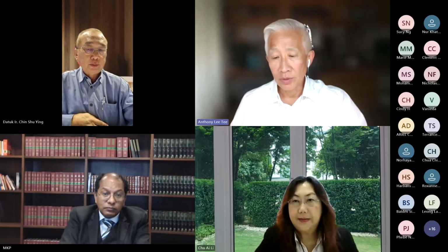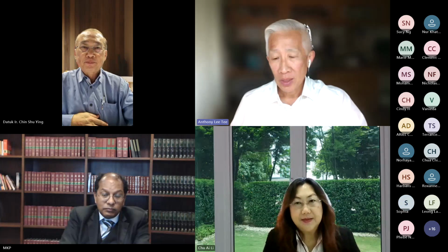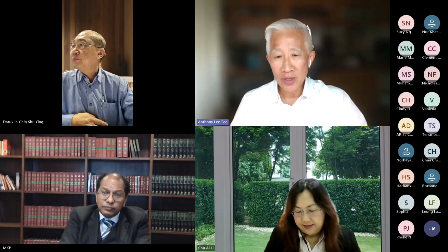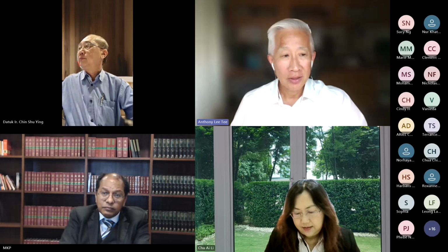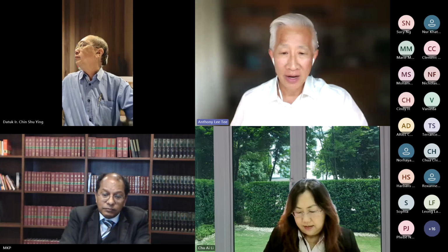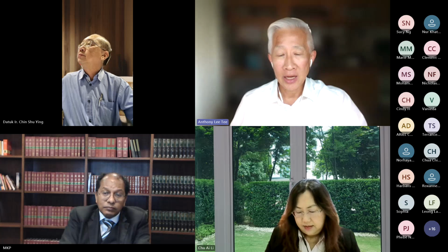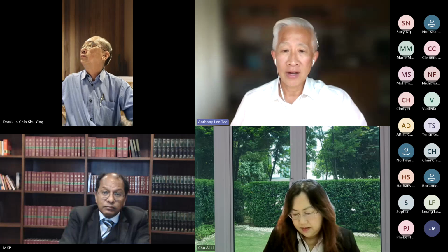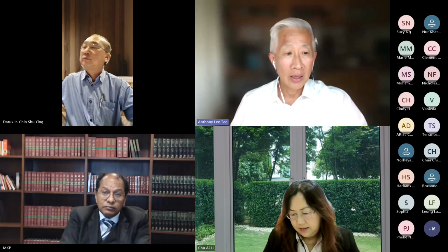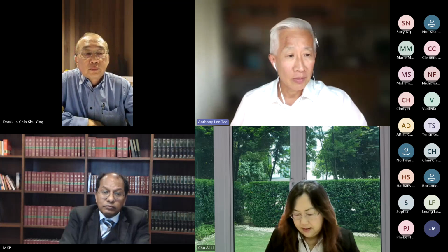Well, that's a really long loaded question, but I think it needs to be asked here. I think also to add to your question, because some of these defects appear much later, laws would have changed. So what would not have been a defect earlier would now become defective. A good one would be the facade cladding. In Malaysia, we all know about the Grenfell fire, when the facade caught fire, and we all saw the fire in the EPF building along the Federal Highway. So obviously everybody started to ask, what are these combustible panels?